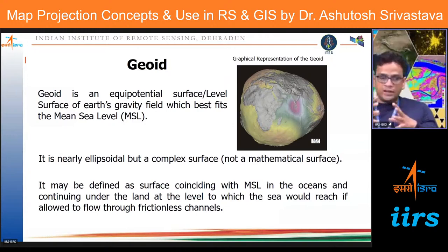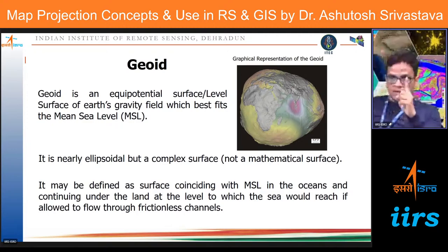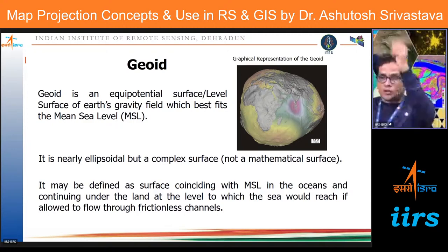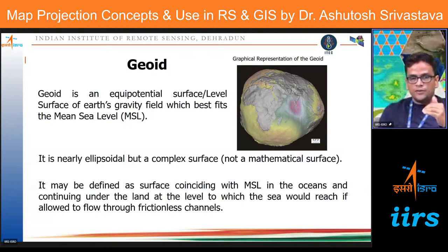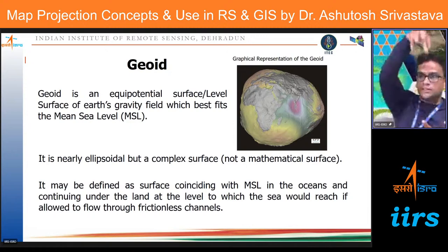So once you generate your ellipsoid, the next thing is to make it more real, so that it can closely represent our Earth. Since it is only an ellipsoid, we have to fix where the north should be, the Earth's rotation axis. So this also we will fix. This is our Earth rotation axis. Where should the equator be? Where should our reference point be? The X, Y, Z triad you have to fix in that ellipsoid.